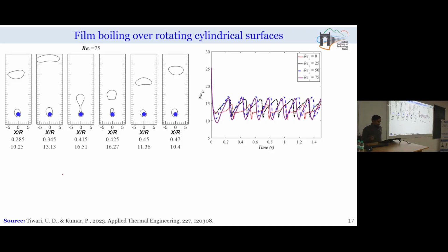Now, one more thing, I have earlier mentioned that if LB and L are comparable, it means that the size of the heater is comparable to the length scale of the bubble. In that scenario, what will happen? In that scenario, we will find that whatever vapor volume forms will immediately completely enclose the entire heater surface. So, there will be nothing like nucleate boiling. Immediately whenever we initiate the boiling, we will enter into the film boiling regime. So, this situation also happens in certain scenarios.